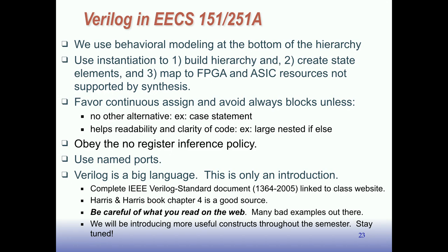We talked about structural Verilog and behavioral Verilog. The way it usually works out is at the bottom of the hierarchy, we use behavioral Verilog. Then we use instantiation, which is the basis of structural Verilog, for building up a hierarchy. And for creating state elements, if you want registers or other kinds of state elements, the way we do it in this class is you instantiate them explicitly.